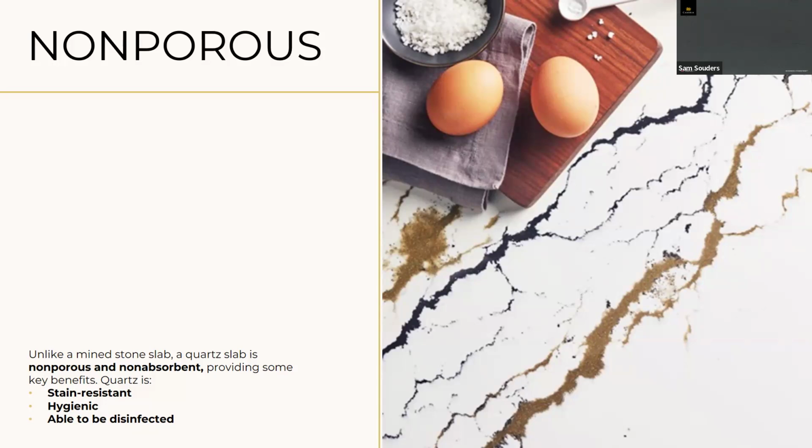For example, making sure there are no crevices on the product where germs can gather and hide allows for easy cleanability, as products with non-porous surfaces will, by nature, provide a smoother, more wipeable surface. A non-porous surface is also more likely to resist stains and won't harbor growth of mold, mildew, bacteria, or viruses. While many quartz surfaces are non-porous, some brands of quartz are not, so it's important to ask the question before specifying.